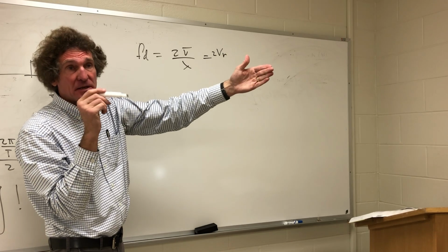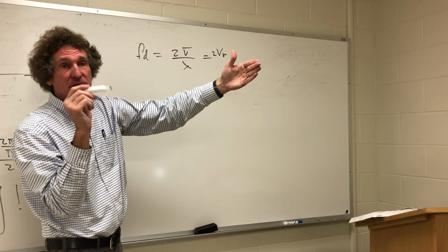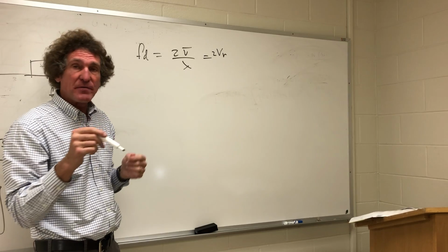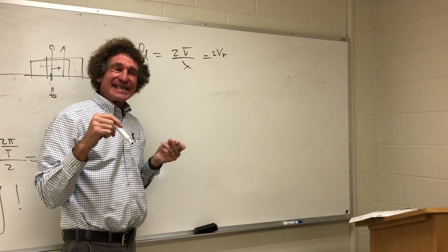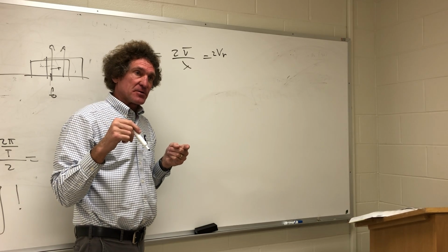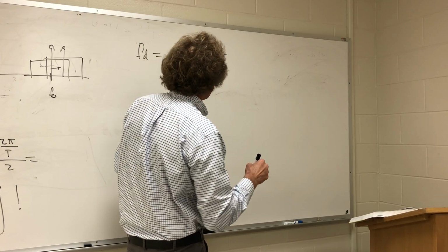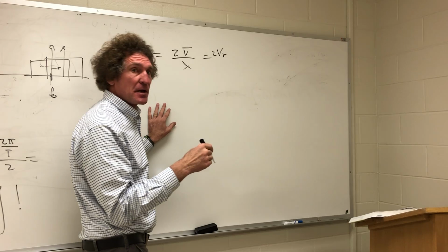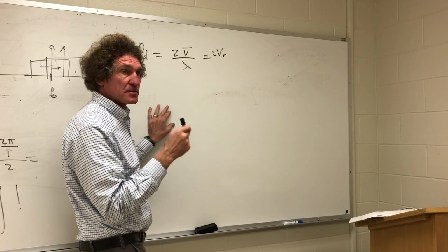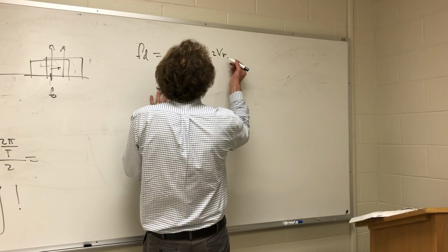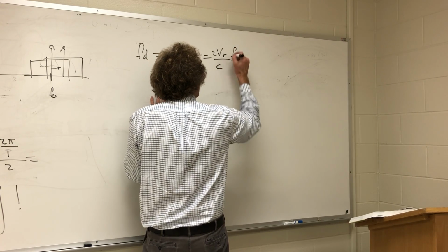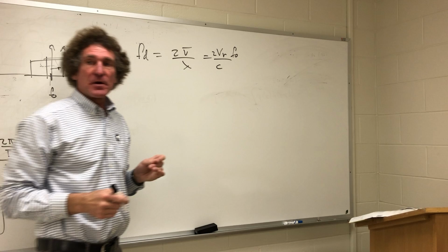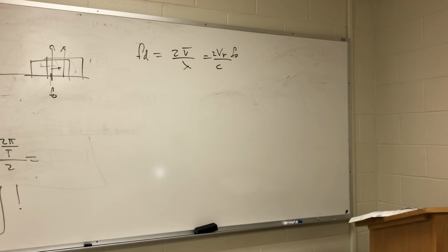You can actually calculate that if you have a ranging radar that's actually taking data. Then you can take the derivative with respect to position, and you get dR/dt, the exact velocity. It's a vector. But we're not talking ranging radars. These are simply moving target indicating radars. And it's 2V, and then instead of lambda, they'll put C and they'll put F naught here. All right, the carrier frequency, gigahertz, 10 gigahertz, maybe 60, 70 gigahertz.